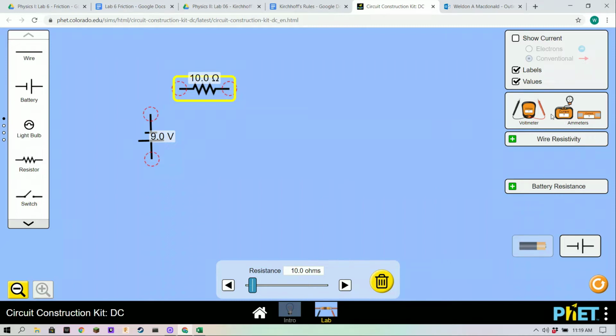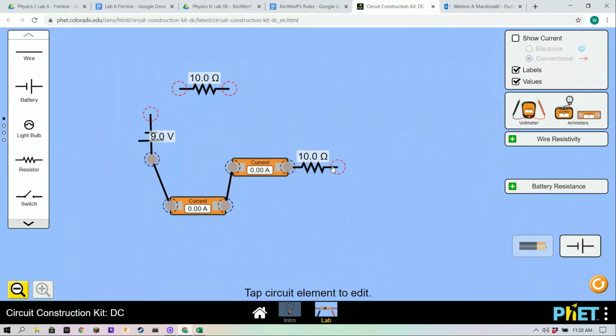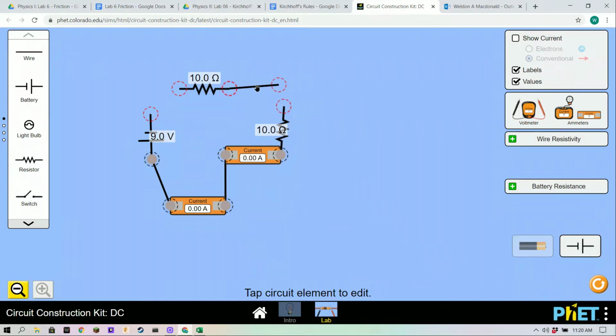There is an extra meter here, but this does not do anything different. I'm not even sure what value it has. The important part here is that you're measuring the currents in the different branches of that circuit. I suggest you actually put a meter in each branch to help you keep it separate and to give you all the values. So that would look, I guess, like this. You're going to have to do a neater job than I have. Remember, you have to take a screenshot.